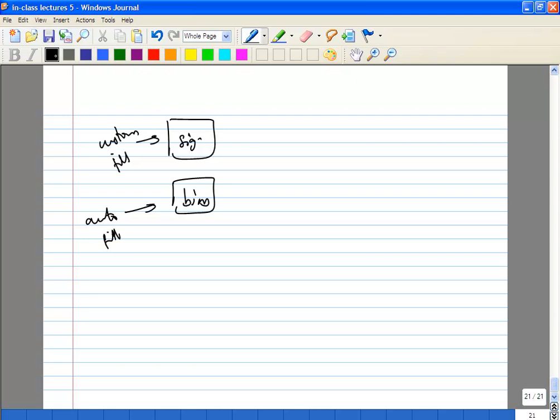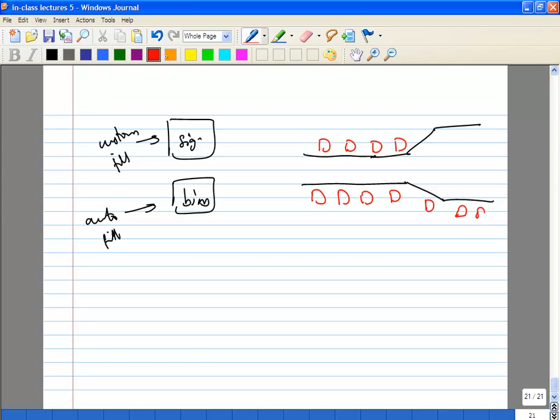And again, let's say you have differential lines. Again, you have to be very careful about the fill. Okay, make sure your fill is symmetric. Something like this. Make sure it's symmetric. Okay, for example, don't fill on one side and not fill on the other side. Don't fill one side farther away than the other side. So those are all things you have to take care of.